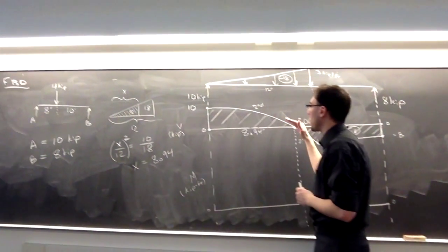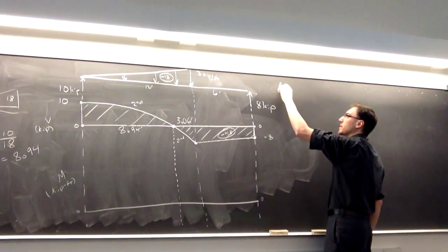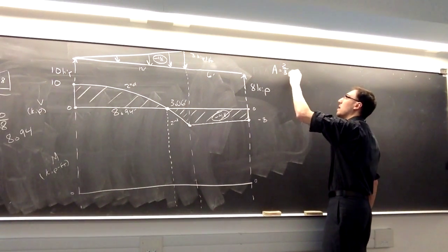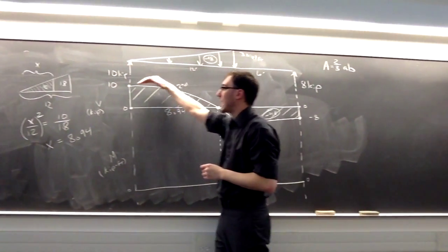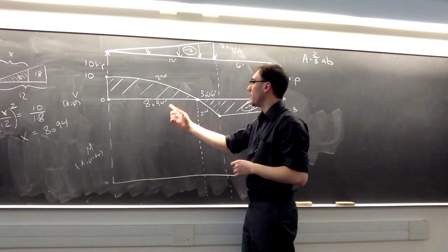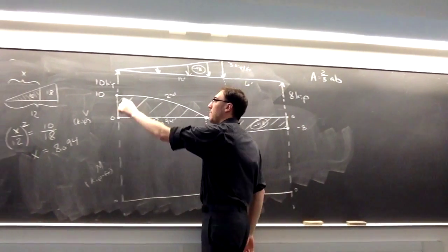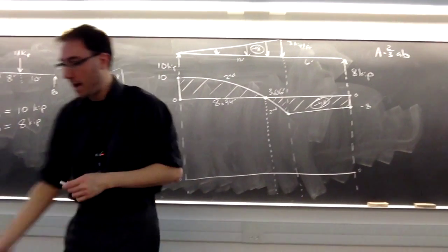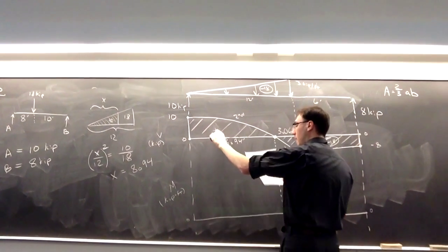So for this one, where the concavity looks like that, what's the equation to calculate the area under that sort of parabola? Right, for the parabolas that are bulging out like that, it's 2/3 the base times the height. That's why it was important to find the base here of 8.94. The height of this parabola is 10. So 2/3 times 10 times 8.94. There will be some rounding in this one, but we get an area of about 59.6.